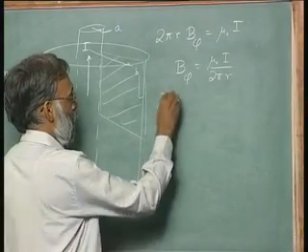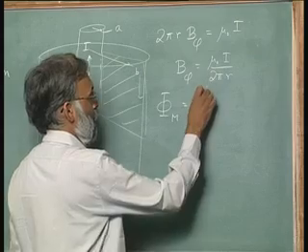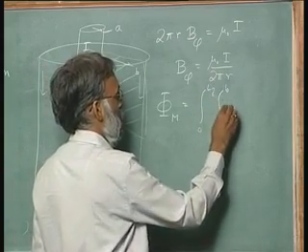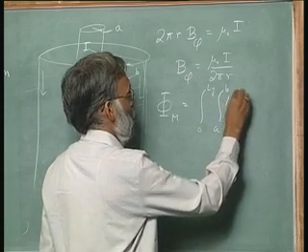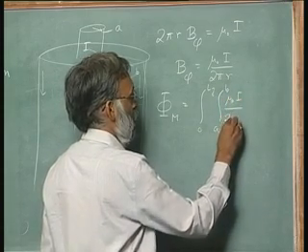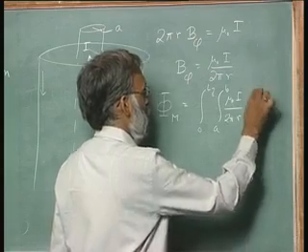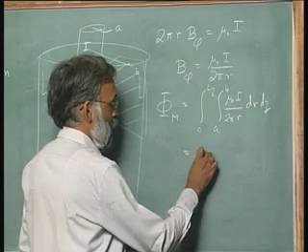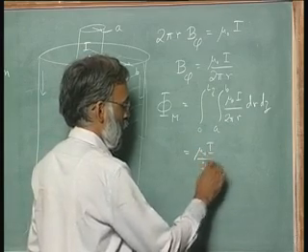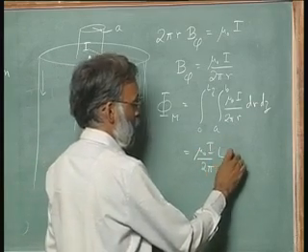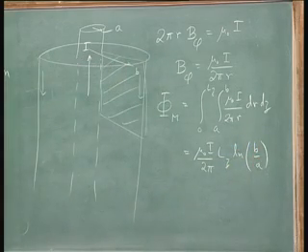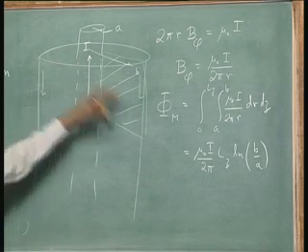So, phi magnetic is equal to the integral, 0 to some Lz, integral A to B, mu naught I over 2 pi r dr dz. It is the same integration. So, we get mu naught I over 2 pi times Lz times ln B over A. So, this is the magnetic flux, it is proportional to current.